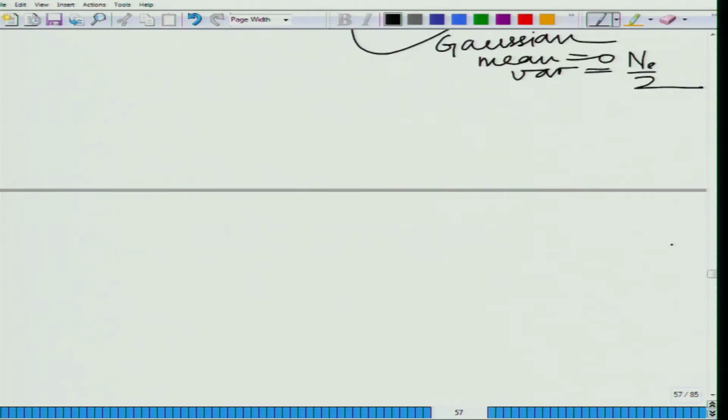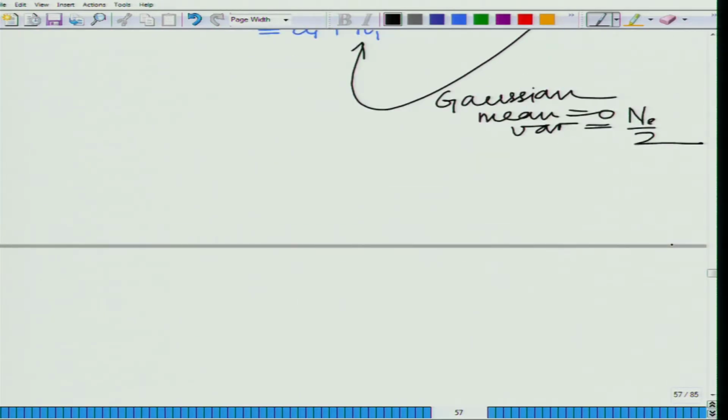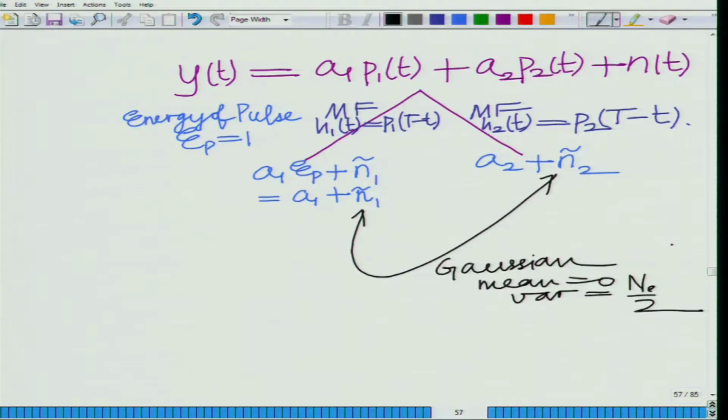And now you see there is a slight change in the detection scheme for M-ary PSK compared to QPSK, for instance, and QAM. What we could do is look at R1(t) and R2(t) separately. Remember, M-ary QAM can be thought of as comprising two constituent square root M-ary PAM constellations.